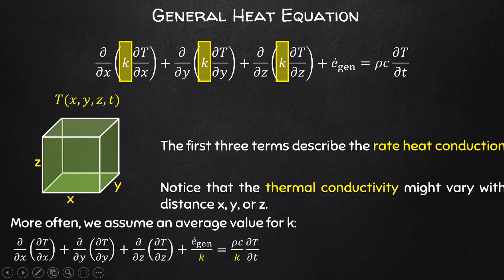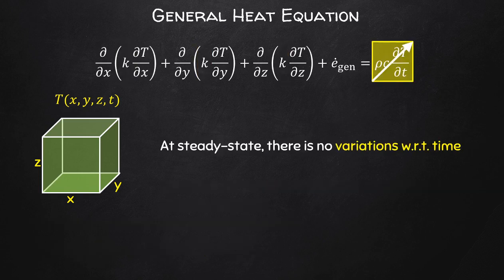So if we treat it as such, we can remove it from its brackets as shown here below. Now, if heat transfer has reached some steady state value, we do not need to consider the right-hand term, which takes into account any variations of time. Okay, so dT/dt: how does temperature change with the change in time?